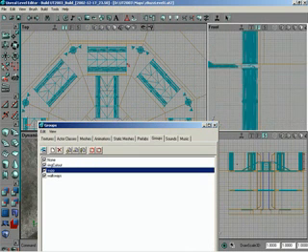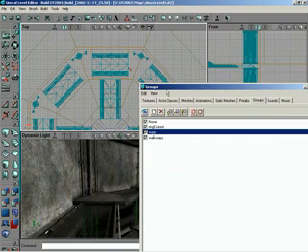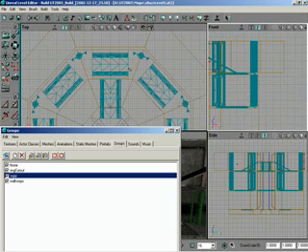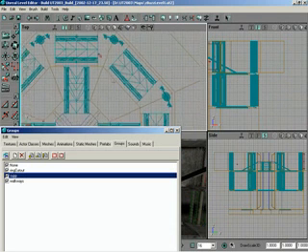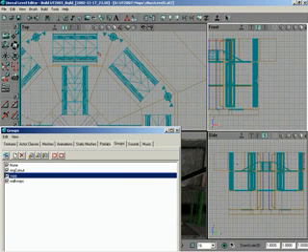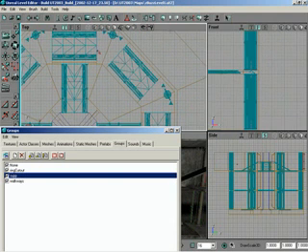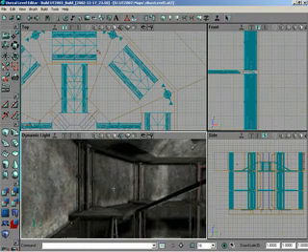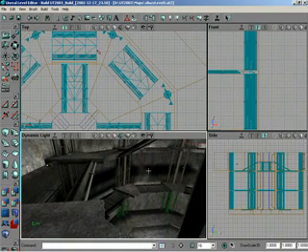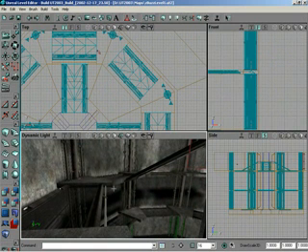Zoom in a little, make sure I have this centered up. Still centered there, good. I still have just those 8, so let me duplicate those one last time. Center them up, and drag them down to the bottom, like such, and still centered, and that should do that. Now we've got pipe supports all the way around. Very nice, and it's starting to look quite interesting, I must say, Logan. Yes, it is. Excellent.